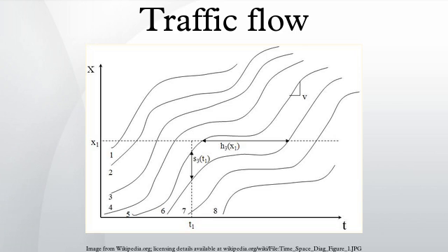N-curve, traffic flow characteristics. The N-curve can be used in a number of different traffic analyses, including freeway bottlenecks and dynamic traffic assignment. This is due to the fact that a number of traffic flow characteristics can be derived from the plot of cumulative vehicle count curves. Illustrated in Figure 11 are the different traffic flow characteristics that can be derived from the N-curves. From these variables, the average delay experienced by each vehicle and the average queue length at any time t can be calculated, using the following formulas.